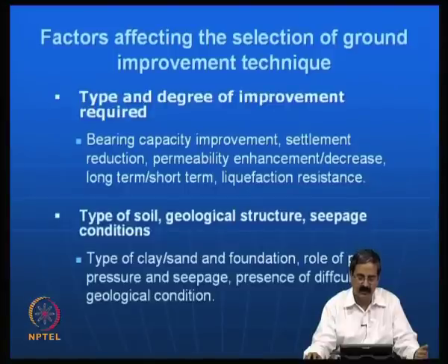It also depends on the type of foundation you want. For example, you are looking at pile foundations as one alternative, but because the cost of piling is so high in India in many places, they wanted to reduce the cost of foundation. So, what should be done? Instead of going for pile foundations, one can provide a raft foundation or isolated footings on the improved ground. The pile foundations you will be placing on the original ground, and then you have to compare with the cost of foundations on the improved ground using ground improvement techniques, and include the cost of ground improvement also.